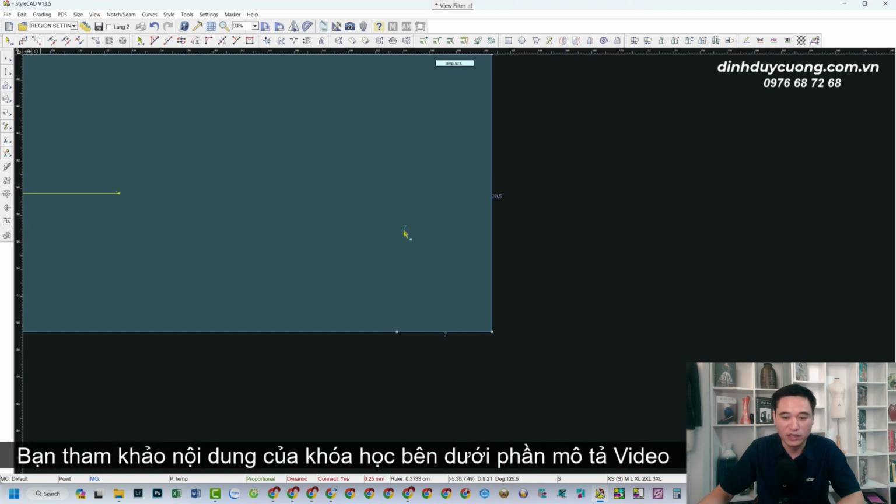That's it. If you want to finish command number 7, just left click, and if you want the neck width to be 6.5, for example, then just enter 6.5. After that, move your mouse close to this point, left click once. So now we have a point here.